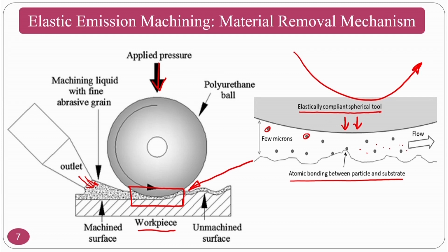What are the chemical reactions that are going to take place, and how the material removal takes place in the non-contact region, is different. As mechanical engineers, what you can guess is that shearing action as well as abrasion is normally the material removal action in grinding, lapping and other things, but in the elastic emission process, this is not so.